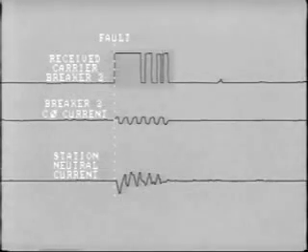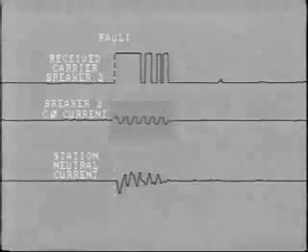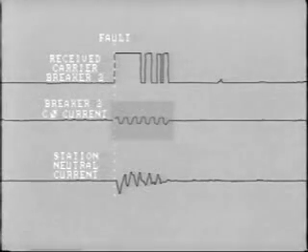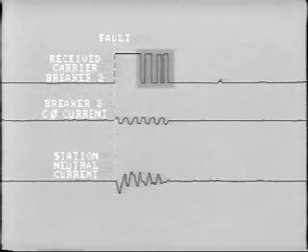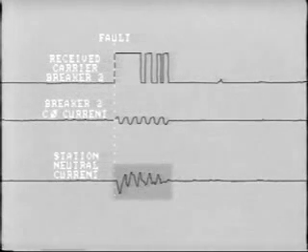Here are traces of the carrier signal that was transmitted from breaker number 2 during the fault, and the C-phase current seen by breaker 2. About 3 cycles into the fault, interruptions or holes begin to appear in the carrier signal. The holes are due to the extreme distortion in the station neutral current, that is, the reference current.